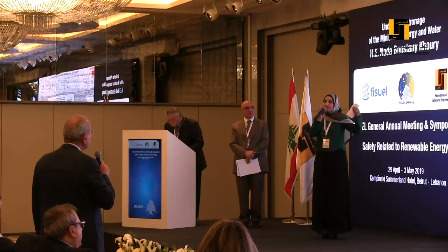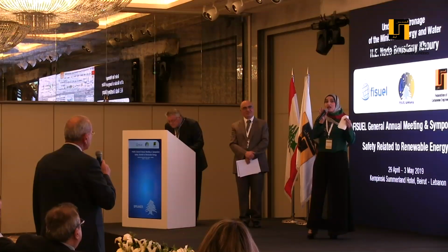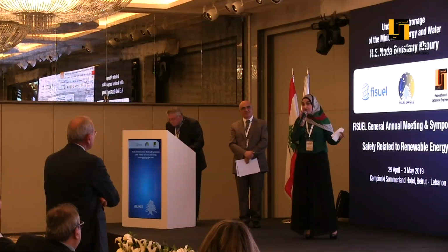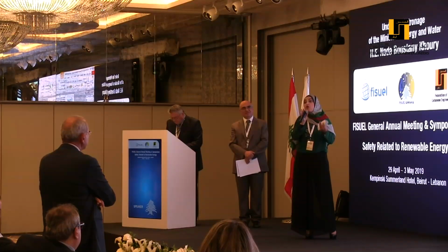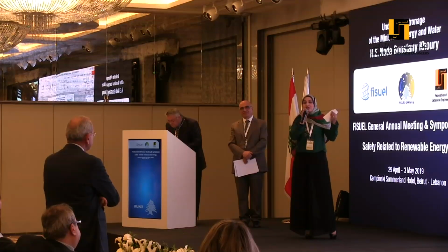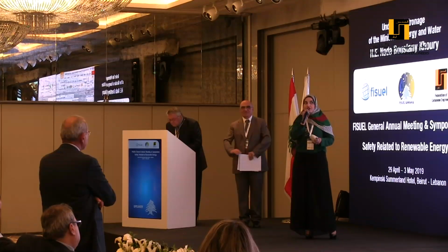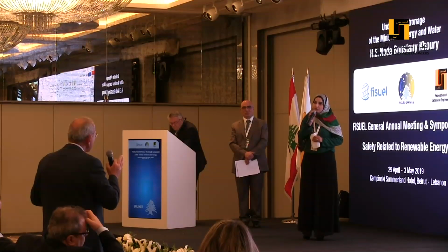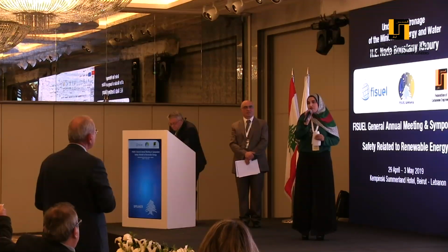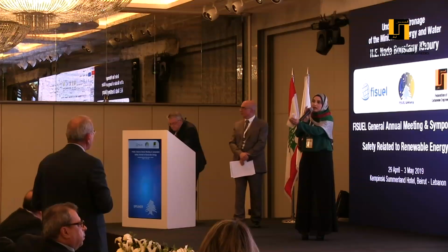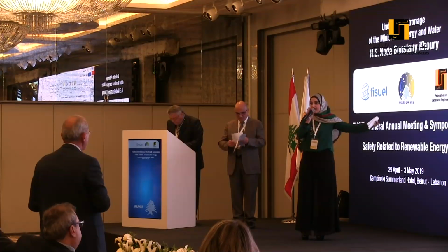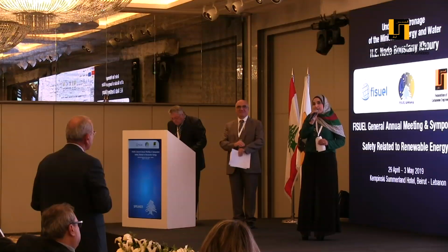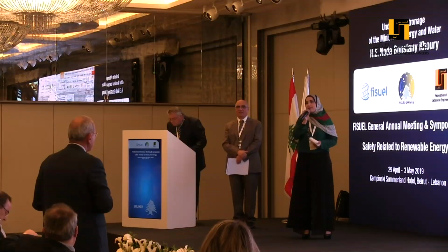In fact, this system is a new technology. The only research we found is on small desiccant wheels. This is the proposal of the first bigger system, but the NASA Center and Burj Khalifa in Dubai use the desiccant wheel before the standard split unit because it reduces the power on the compressor. But there is no significant research done for bigger scales; it's for small ones. It is applicable, of course, for bigger scales, but I think it needs a plant near it to power it because it needs a big area. But it is applicable for all, for smaller or bigger scales.